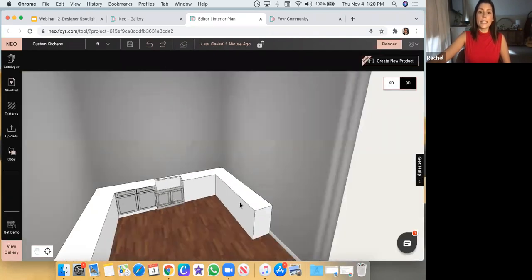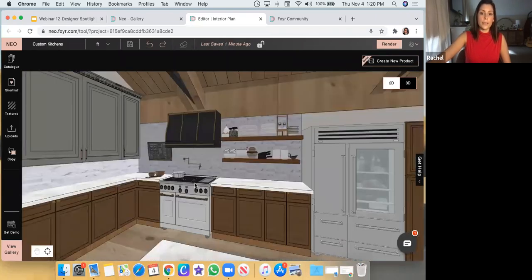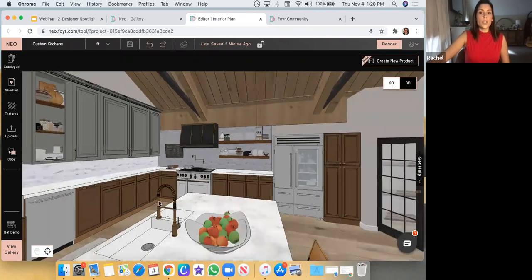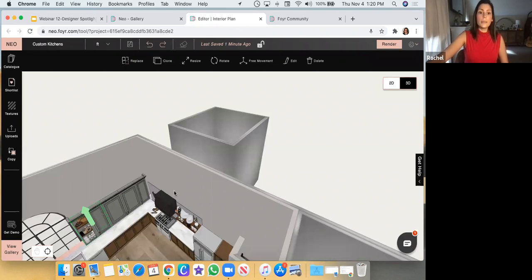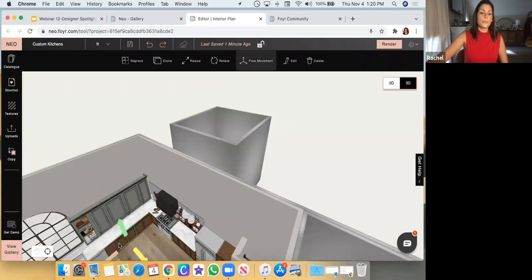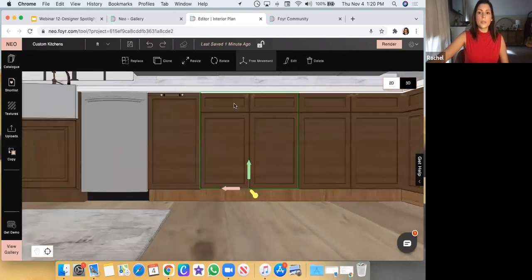All right, so I did the exact same process for the stove here to create the cavity for the stove. Placed my cabinet shutters over top, applied my textures, and then went into the catalog and looked up handles and knobs and found those. Double click here and applied them. So I've got some pulls here and some knobs.